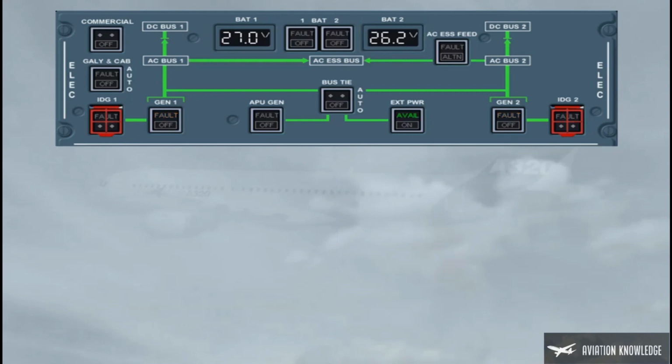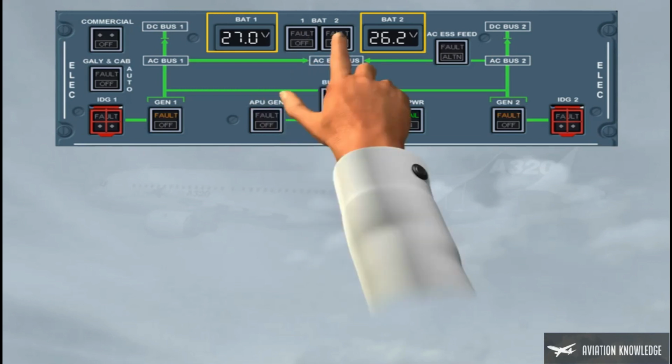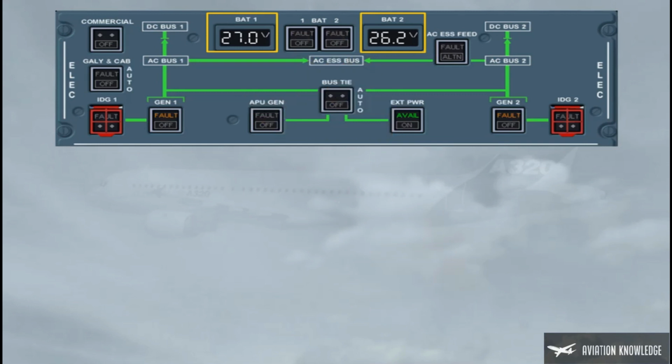But, before powering electrically the aircraft, if it has been electrically supplied during the past 6 hours, the related battery voltage will be above 25.5, ensuring a battery charge above 50%. So the batteries must be switched on. Now, if the APU has to be started on battery only, make sure to start it within 30 minutes following the battery selection to on, because the charge of the batteries will be less than 25% if they still supply the aircraft's after 35 minutes.